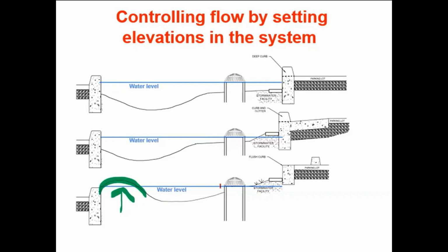So you've got two choices here. One, you can definitely lower the level of the raised drop inlet, but two, you can raise the level of the land over here to create a berm so the system does not overflow. All of these are available for you as designers to help make this system work. What this means, of course, is that you have to have a lot of spot elevations to make this function.